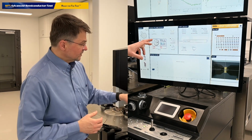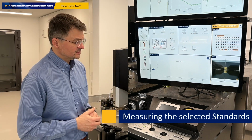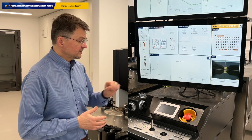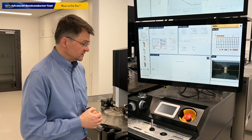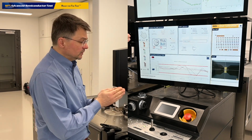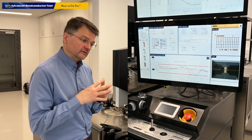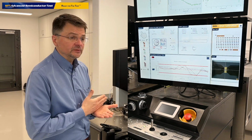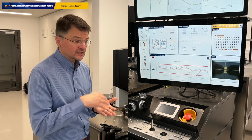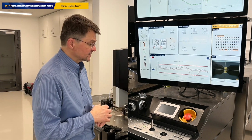Okay, now let us move to the first standard. I've selected the through standard, move to the through manually, go to the contact, I land the probes in the contact, and I trigger the measurement process by simply clicking on the Smith chart of the VNA widget. By doing that, we will measure two different types of quantities. First of all, we will look into the repeatability of our measurements, and Calibria does repeatability data verification on a different sweep, different to the main sweep. We check data repeatability on a smaller number of points, and the sweep can be configured to any different start and stop frequency points than the main sweep.